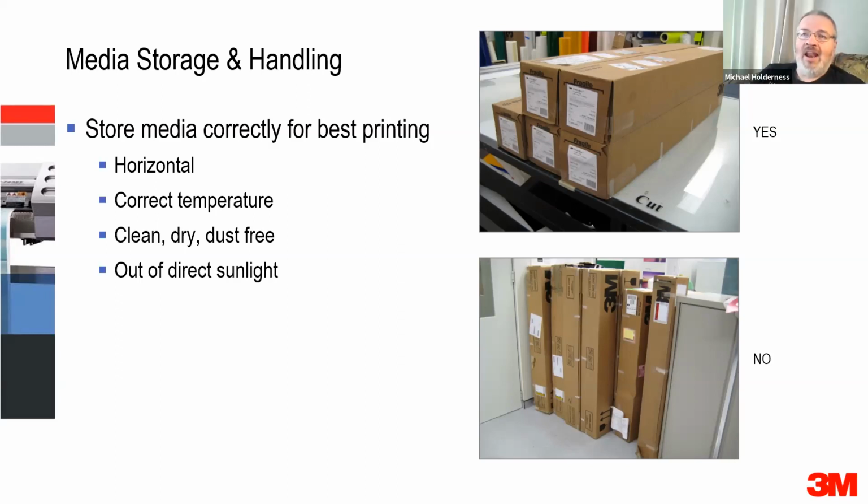Generally, you'll find that one lamp at a time is what's done, but it's going to depend more on what you do. If you've got a particularly difficult media that you're finding hard to cure, you can turn on both lamps. Some printers will have the ability to alter the power rather than the temperature on the lamps. And I would generally say I would lower the power on the trailing lamp to give it a little bit more time and then finish off the cure with the leading lamp.